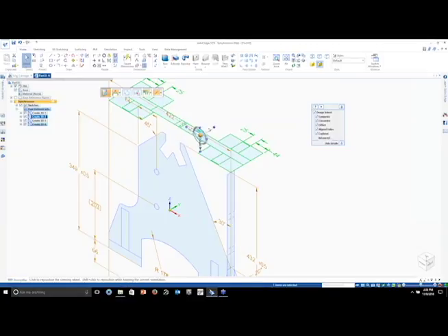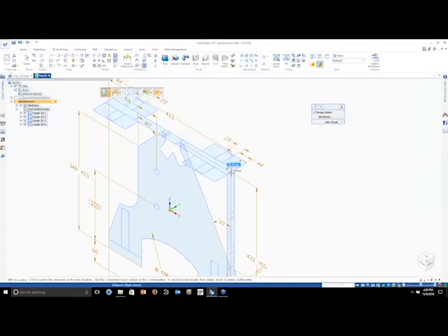All right, so now, since I brought this into a part file in Synchronous, those sketches turn into regions. So I'm just going to start grabbing my regions and applying the thicknesses using the other sketches. And you're going to see what's going to happen here once I start doing that. So again, just by using my select tool, grab my region.